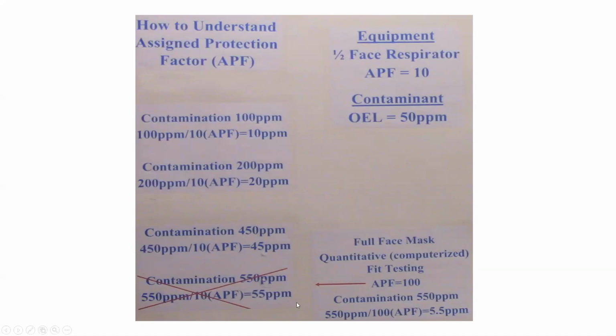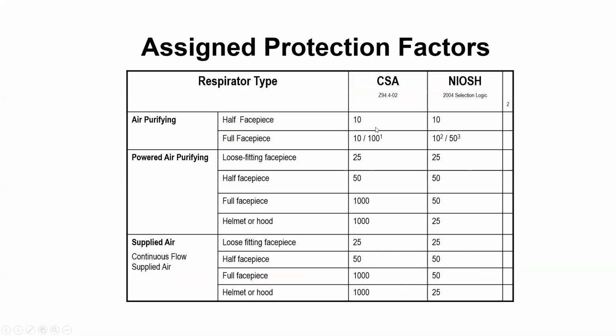However, what we can do, we can use a full face mask where workers were fit tested with computerized equipment like QuantaFit or PortaCount. Assigned protection factor is 100.